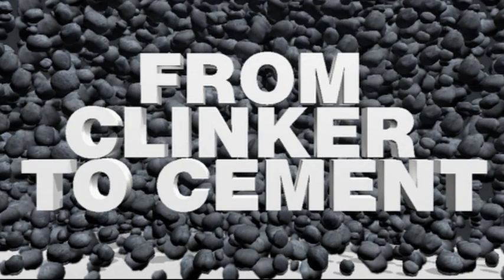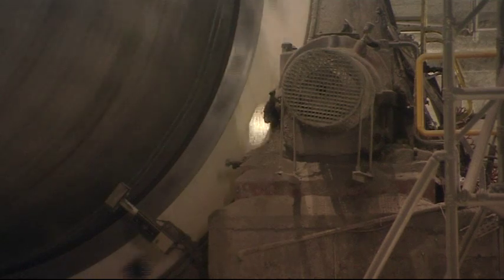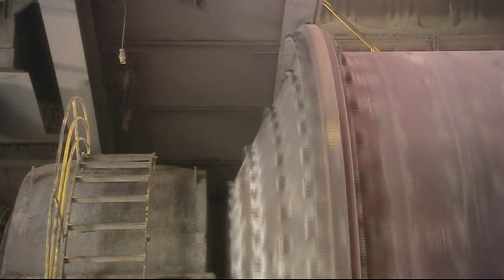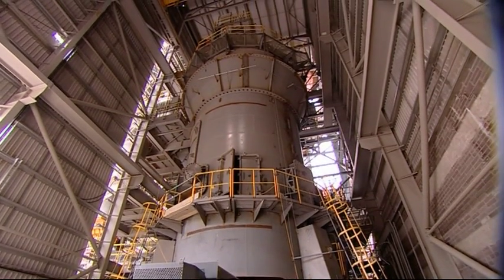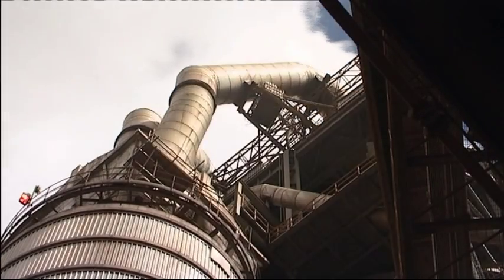The clinker is milled in cement mills. A small proportion of gypsum is ground with the clinker to control the rate at which cement sets. Cement mills have high efficiency separators which optimize power consumption. Unburnt limestone is also now introduced to the mills in the production of new, lower carbon intensity cements.